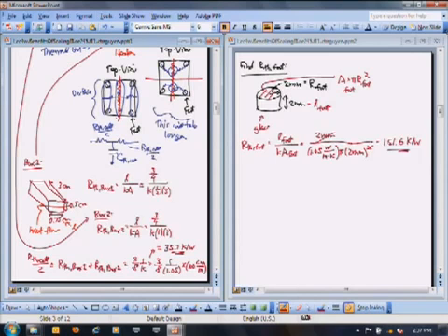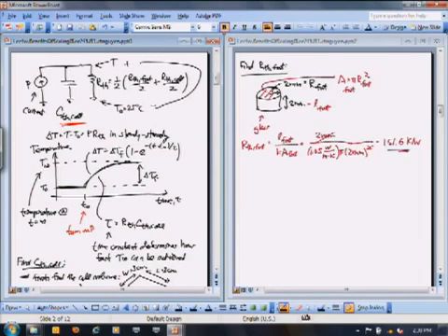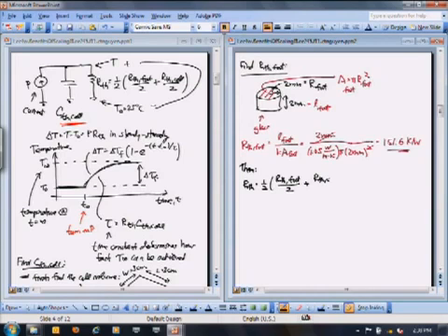Okay, so I can now find the total thermal resistance that I need right here in this circuit here. So RTH is going to be equal to 1/2 of RTH of a foot divided by 2 plus thermal resistance of the cell divided by 2. Plugging in numbers, that's 1/2. So the foot was 151.6 divided by 2. The cell I already calculated divided by 2. So that's just going to be 35.7. And this whole thing then boils down to this thermal resistance in this problem is 55.8 Kelvin per watt. And so now we have the thermal resistance in this circuit. We have the thermal capacitance of the cell, which we got last time. We can now calculate all sorts of things about this problem.